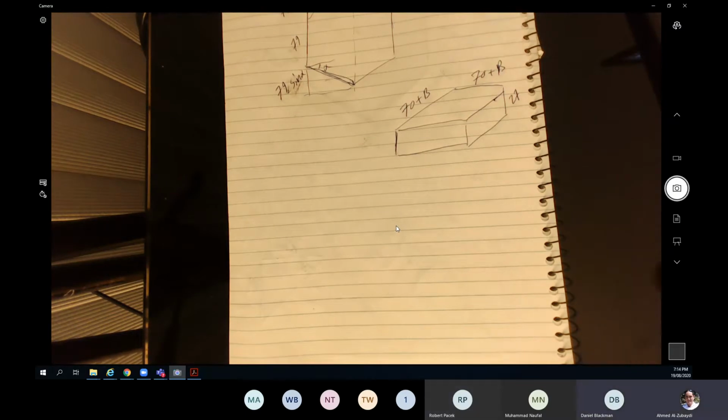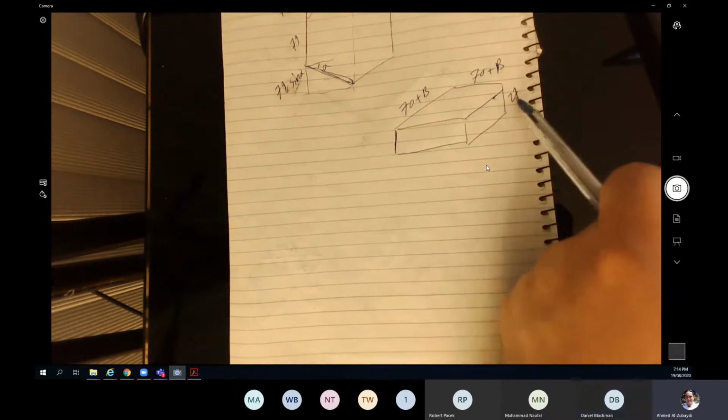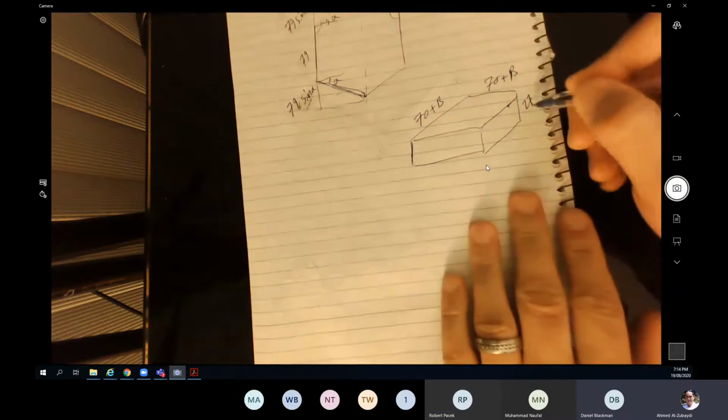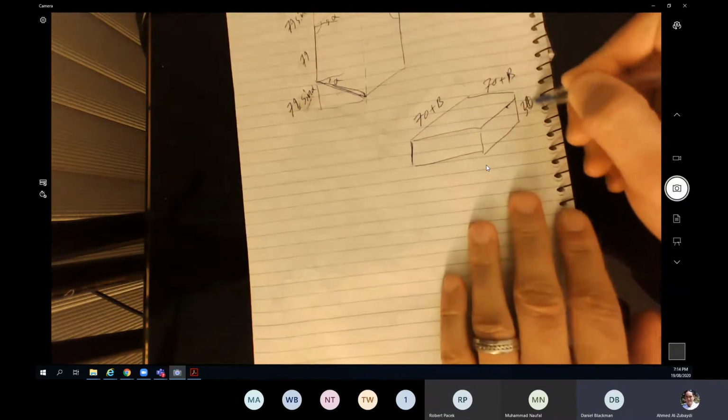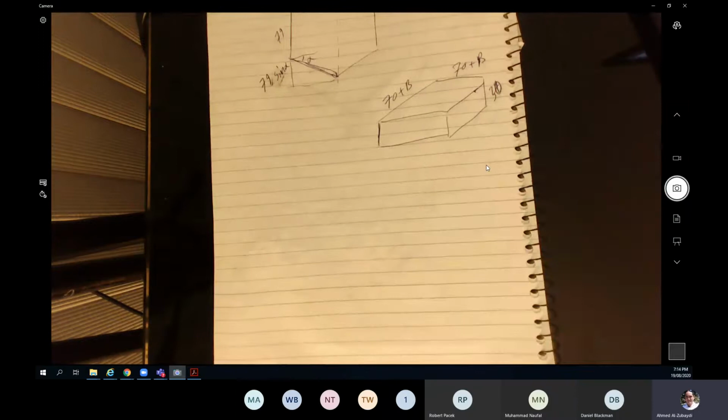If you search online for a block material to start your machining with, you'll hardly find 27. You'll find 20, 30, 40. Okay, so in this case, we're going to add 3 millimeters here, and the starting block is going to be equal to 30 millimeters in height. But the height I would like to have at the end is going to be equal to 27 millimeters.